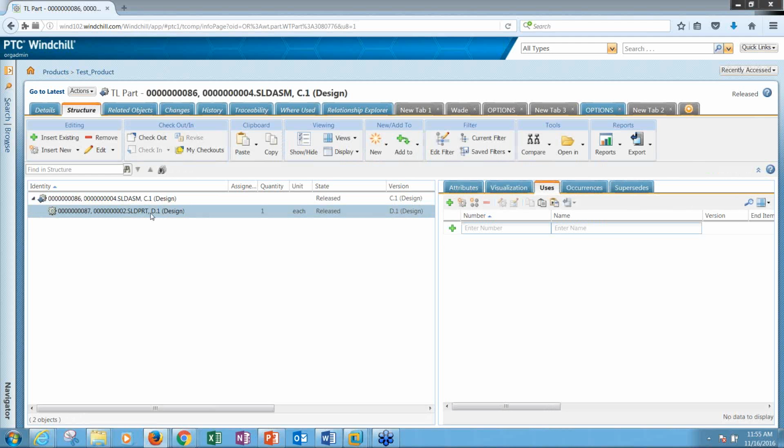So that's an example of, okay, I have this minor change I need to make to a subcomponent somewhere down within this assembly. Do I need to revise the top level assembly so that I can see Rev A use Rev A of this component and Rev B use Rev B of the component? Well, not necessarily if you're using baselines to track those types of lower level changes. So I can have Rev A of the top level assembly, but then I can have baseline Rev A01 and Rev A02 that represent those different configurations.